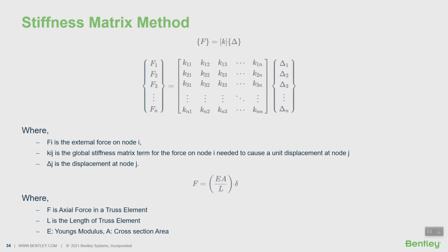Grouping all the small matrices together, a stiffness matrix for the entire structure is created. Once it is established, the unknown displacements of the nodes can then be determined for any given loading on the structure. When these displacements are known, the external and internal forces in the structure can be calculated using force displacement relations for each member.